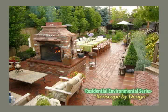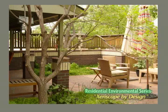So this is a great, I should have put the before of this in here. It was so sad. Here we have clay pavers again. And this is interesting because this area that has the roof on it was an old concrete patio, and we overlaid the pavers right on top of the concrete up to where that joint is, where that flagstone mortar border is, and then the part going out where the table is on road base. And this picture was taken probably 5 years after we installed this project, and it hadn't settled at all.